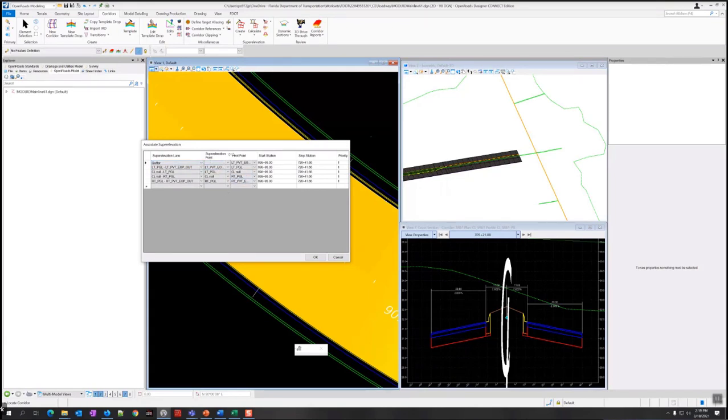And it should, because remember, it generated all of these from the template. So it should get them right, but it's worth checking. So I'm going to start here in the center. So center line null to left PGL. It pivots about the center line. Well, actually, maybe I should start about the right side because I was pivoting about the right side in this case. So pivot point for this right lane is the pavement out, and then super elevates the PGL.